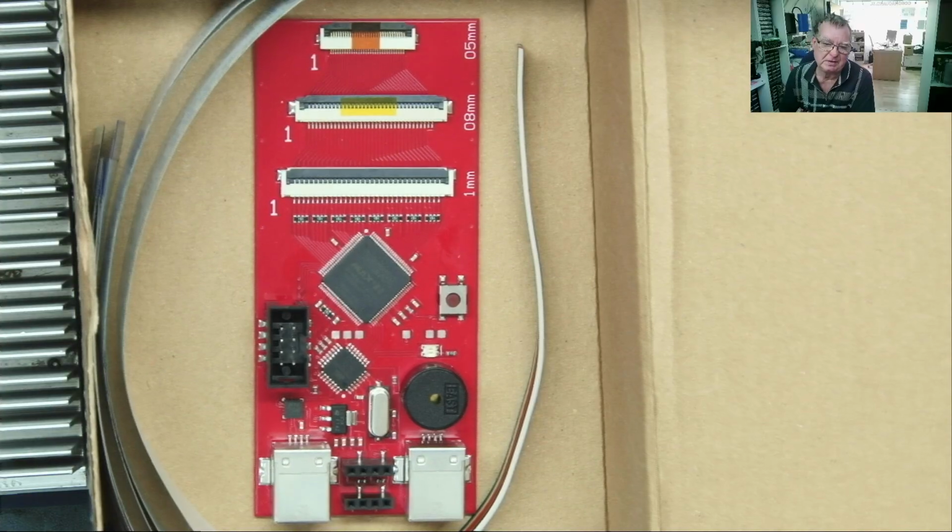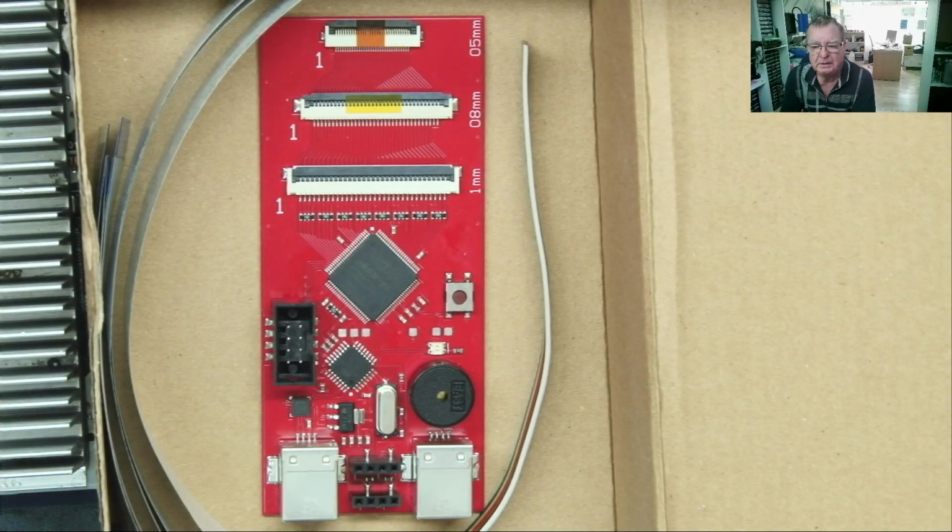On a laptop, for example, a lot of laptops will fail, it won't start up. Disconnect the main battery, which is usually inside the thing these days, take it apart, get the battery off, make sure there's no CMOS battery, leave it for 10 minutes, put it back together, it will work. Yeah, that's because the firmware in the EC chip, which is responsible for the startup, got corrupted, but it can kind of sort itself out.